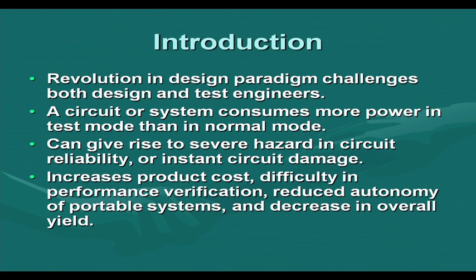So, when we are doing a delay test, it may happen that a chip will fail in the delay test, though the chip is actually correct, but due to this heating, these delay differences have occurred, and as a result the chip gets discarded. Or it may happen that a chip which has a delay problem passes the delay test due to this uneven heating, and a bad chip is shipped to the customer.